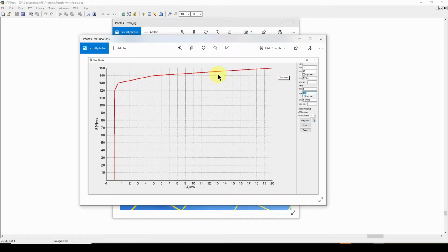And then, once we've got that in the simulation software, we're going to check it against the actual current flow we see in the transformer when we're applying, say, 220 volts. We'll see if that matches up with the software simulation so that we know we've got a good model.